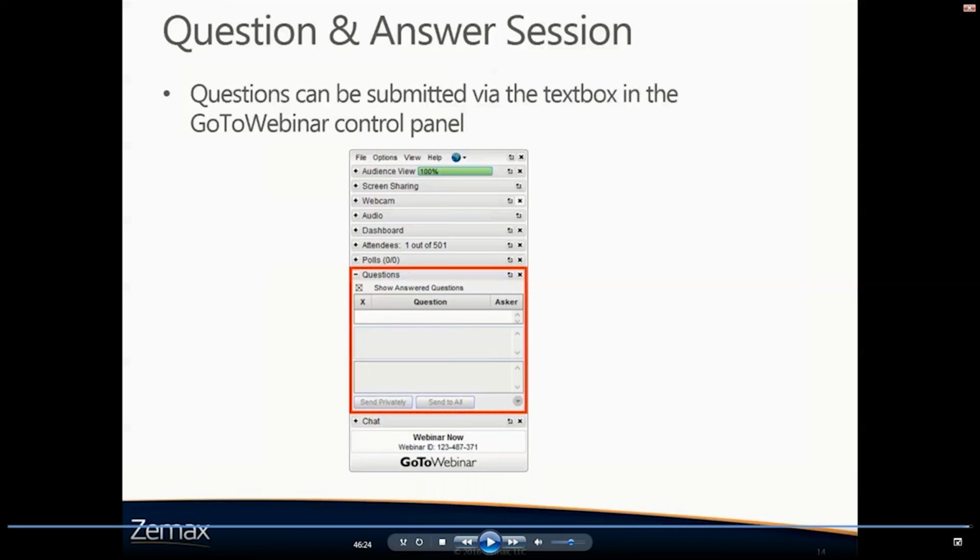And then I guess the final option for combining a Lambertian and an ABg scatter model would be to do some mathematical modeling of how much scatter goes in each polar and azimuthal angular direction relative to the specular ray, and then you could sum or average those two scatter profiles and create a BSDF file that you could use in its place.